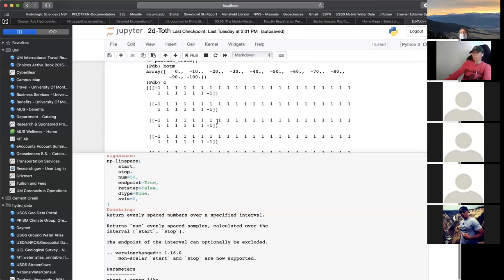So the default boundary condition, if we have a bunch of cells and they just end, then MODFLOW automatically sets the conductance out of that cell equal to 0, and it's a no flow. So the left and the right side and the bottom can all have an I bound of 1.